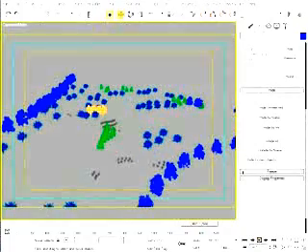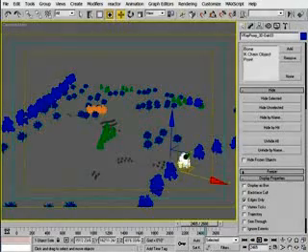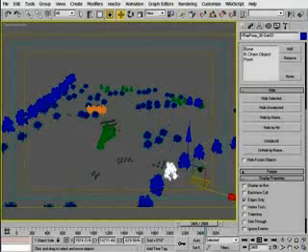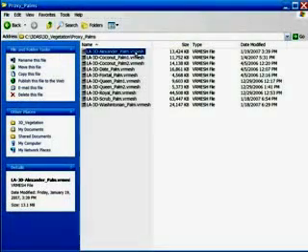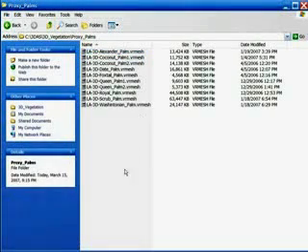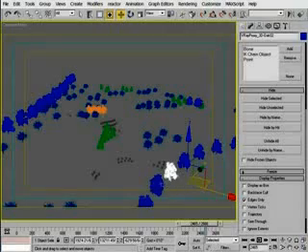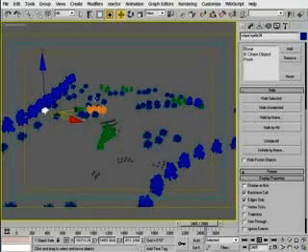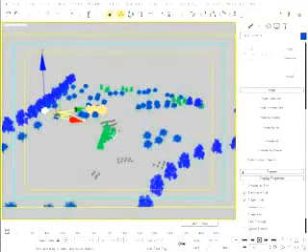It's simply a placeholder for a real object whose structure is defined by the data in a separate file known as a VRay mesh file, and that file has the extension .vrmesh. The data required to store a proxy, i.e. the placeholder, is virtually nil, and you could therefore have thousands of these proxy objects in your scene.